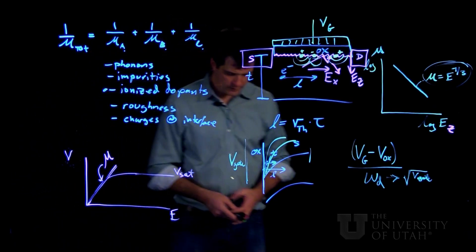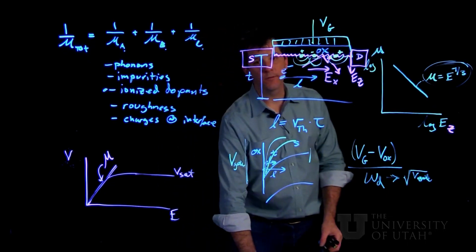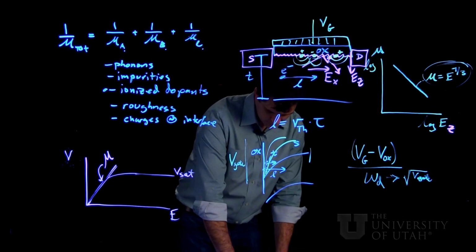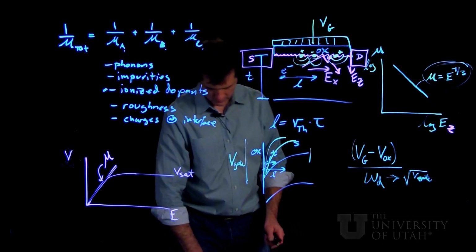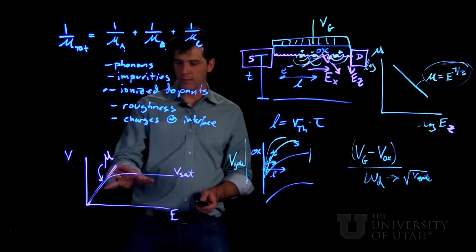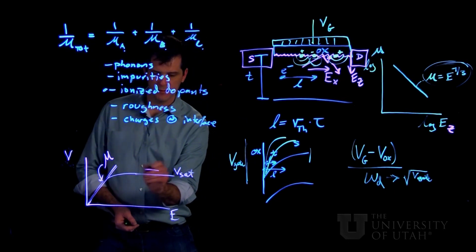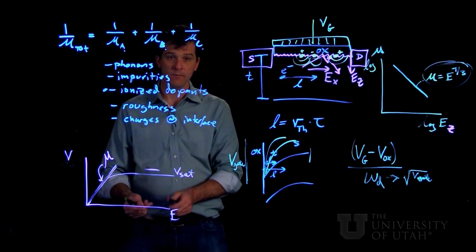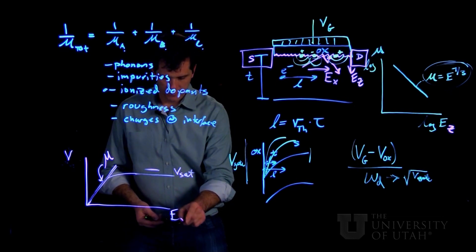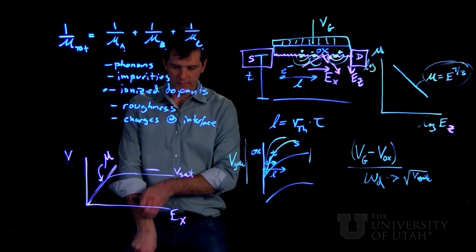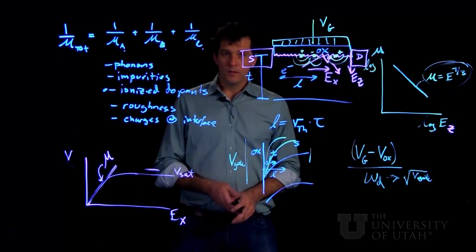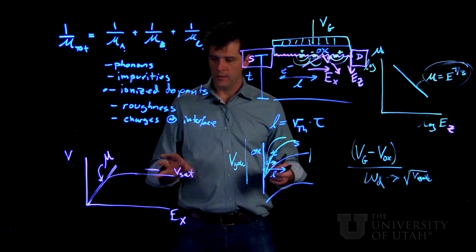So in the derivation of the IV curves for the ideal MOSFET, we've assumed that the mobility is constant, but the mobility, the differential mobility, essentially goes to 0 out here in the saturation velocity regime. And this E field that we're talking about is our EX, the lateral one causing lateral transport. So let's look next at what happens because of this effect.